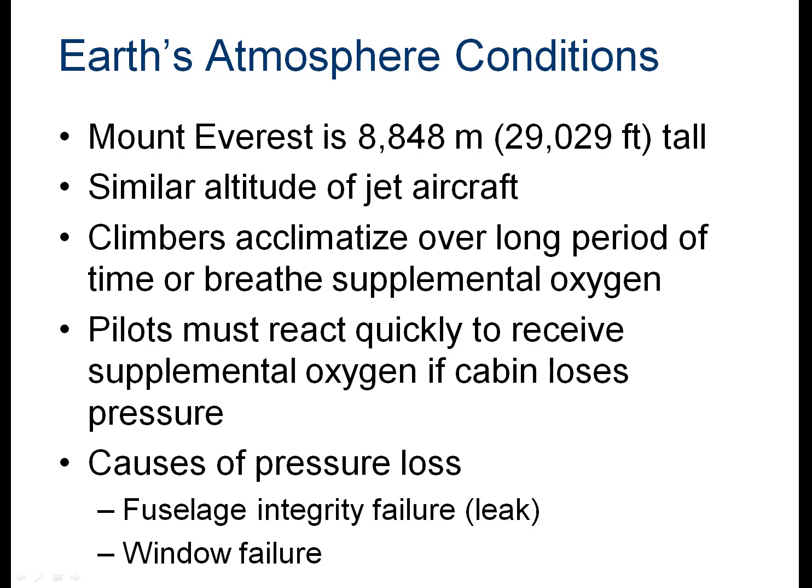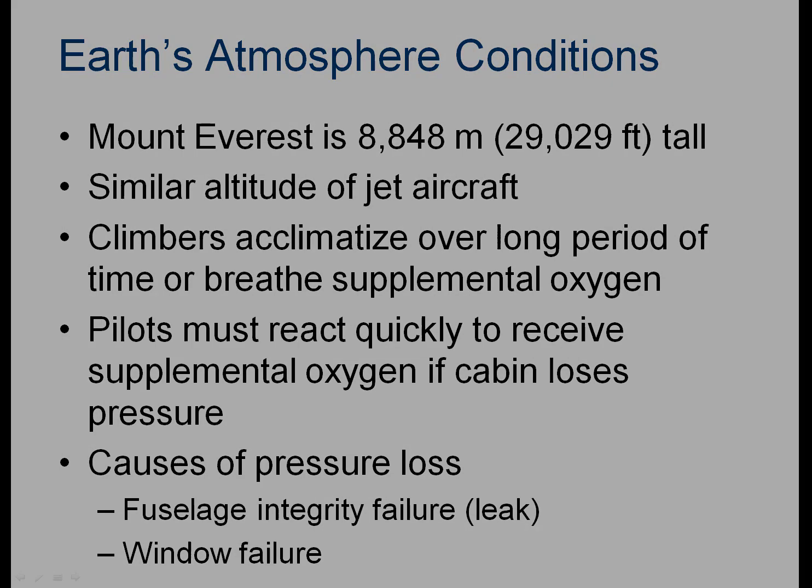Now, the other reason that airplanes don't fly above 40,000 feet generally is because the pressure differential required is really high. So if you go to 100,000 feet, you need to have a tremendous pressure vessel to hold in the difference between the outside pressure and the inside pressure.